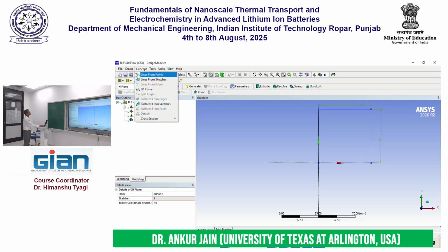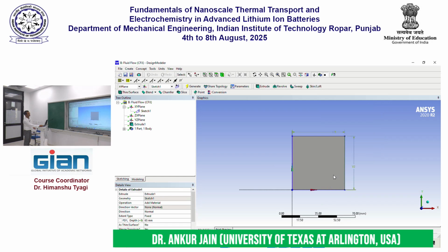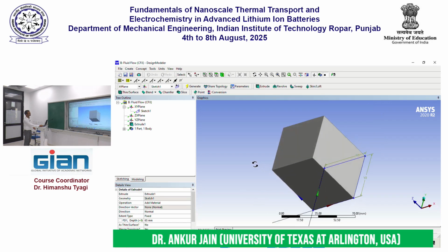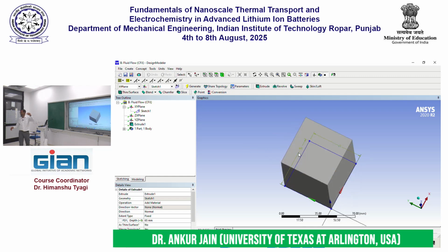I'm going to extrude it. Hopefully this looks familiar from the work that we did yesterday. And the cells are 65 millimeters tall, so I will extrude it to 65 millimeters, and this is my base. This is my battery pack, right? I have to build two holes in it in order to insert my cells.